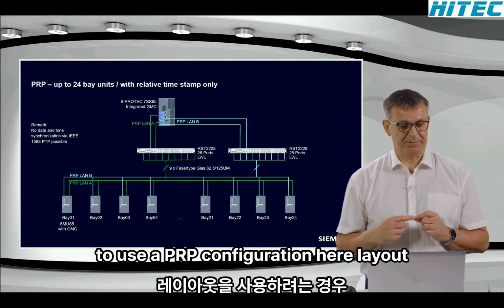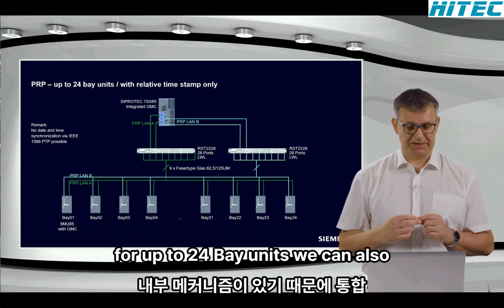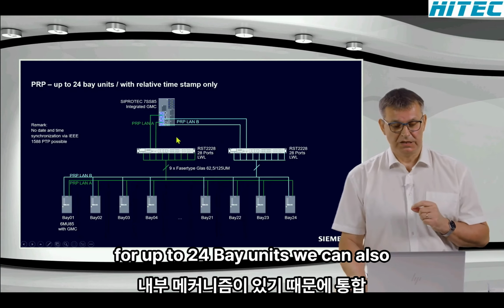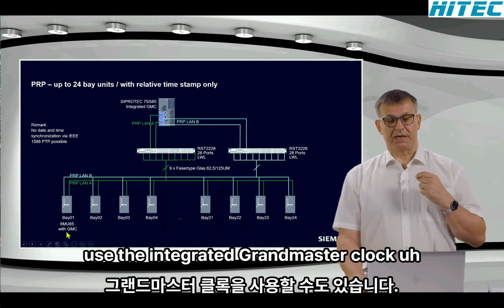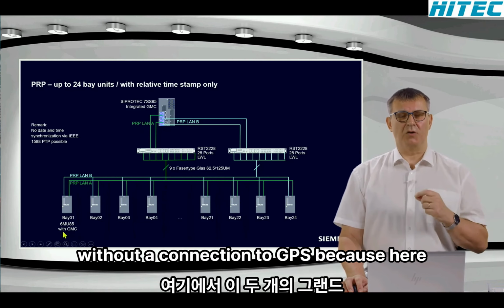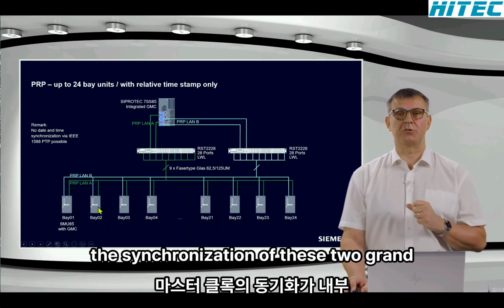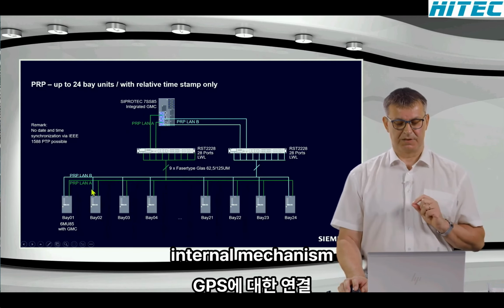If we want to use a PRB configuration layout for up to 24 bay units, we can also use the integrated grandmaster clock without a connection to GPS, because here the synchronization of these 2 grandmaster clocks will be handled by an internal mechanism.